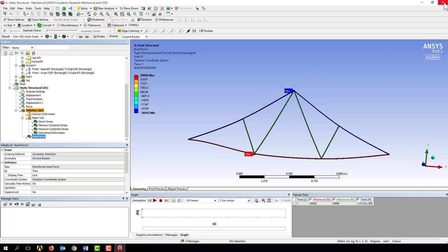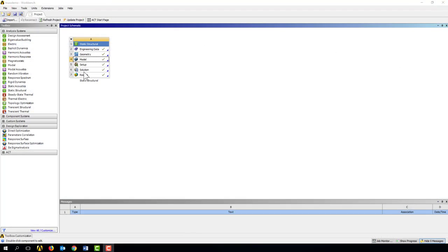So I'm going to go ahead and close this Ansys Mechanical, so we go back to the Workbench tab. Down here, at the top, there is eigenvalue buckling. If I drag that over here and set it down on top of the model, it's going to tell me I want to share the data between those, and it's going to automatically draw these. I could do it manually, but this is easier. Now I also need to know the loading type, and I can grab that from the solution, drag that across to the setup, and we see it wires those across. And I've already got green arrows down here, and this one's ready to go.